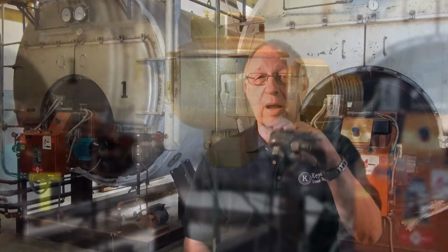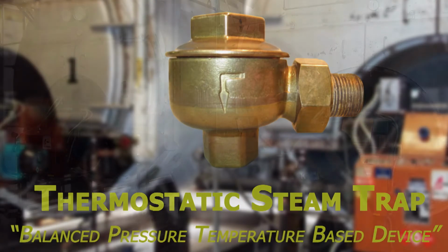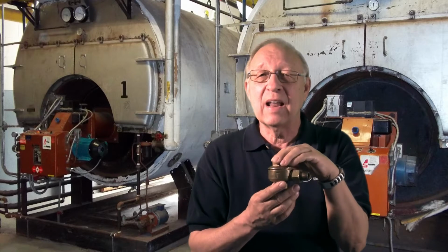The most common type of steam trap is a thermostatic trap. The thermostatic trap is a balanced pressure, temperature-based device, meaning that it responds to the difference in temperature as between steam and hot water, or steam and air. It's most commonly found at the end of radiators in heating systems or after machinery in process work applications.